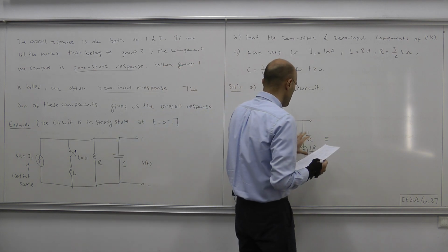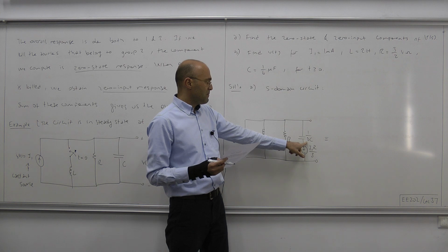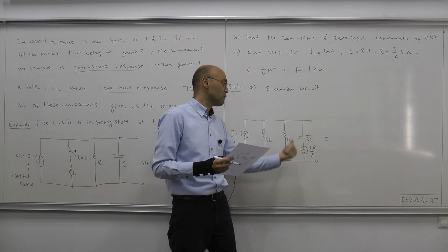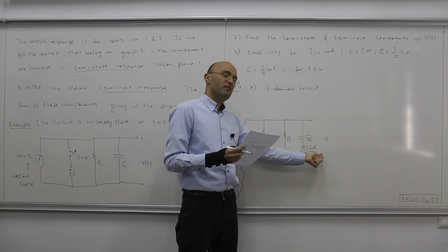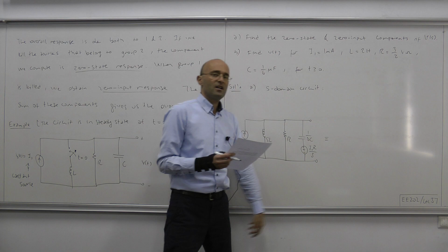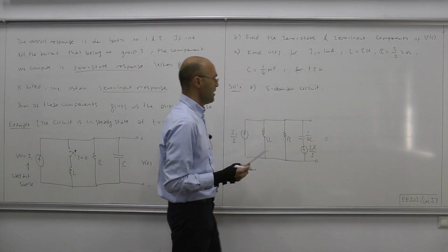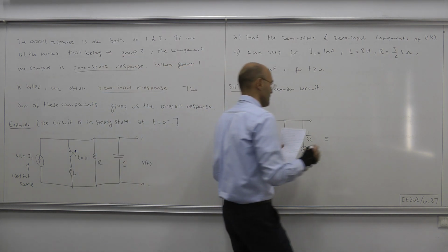Okay, so if we apply source transformation to this, what we have is the impedance will be 1 over SC, and then the current of the current source that will be parallel to that will be, in a sense, Thevenin voltage divided by Thevenin impedance. Okay, I1R over S divided by 1 over SC, that produces I1RC.